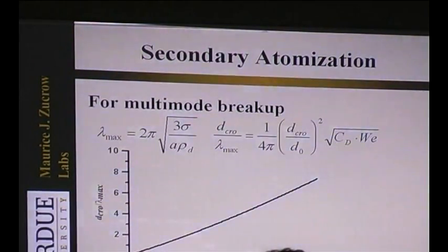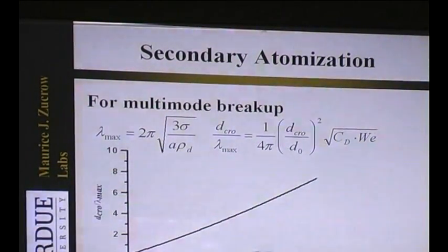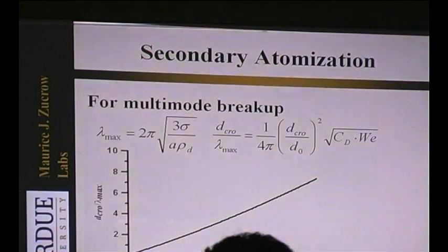we don't get particularly good agreement between linear stability analysis for the number of cross-stream wavelengths in the disturbance and the actual Weber number. We notice that we're getting somewhere around 2, which is good news, but when we get out to a Weber number of 80, we get around 5 or 6 nodes, and that's not what we actually observe in an experiment. So if we go to the next slide,